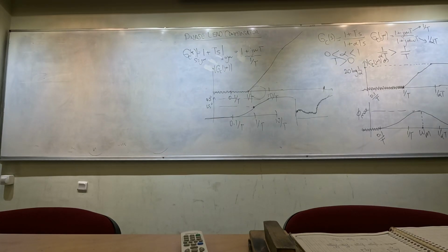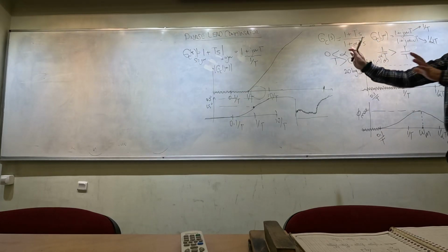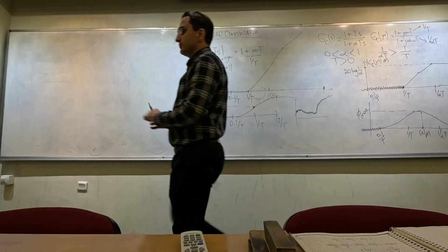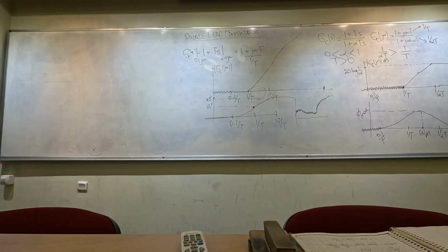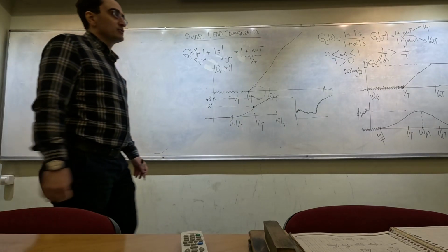If you want to use PI or PD controllers, you have to spend some power. Only using an op-amp can you come up with a derivative circuit or integral circuit, and your op-amp is going to spend some power. But these compensators can be implemented with passive elements only, meaning that you don't have to spend energy for your control.